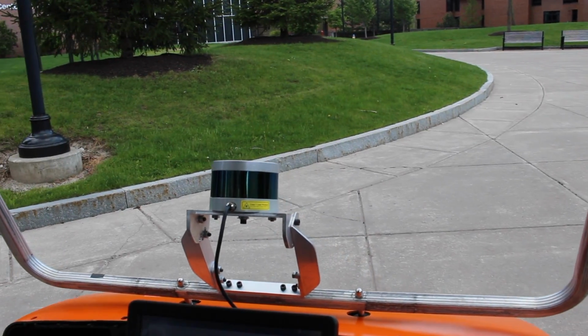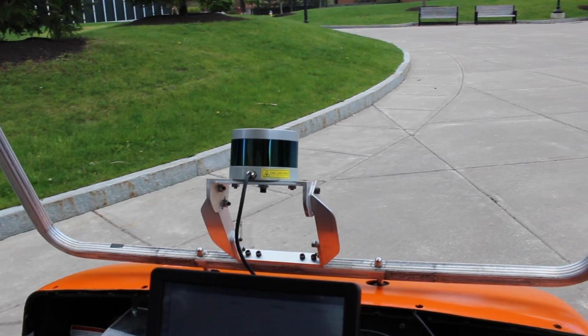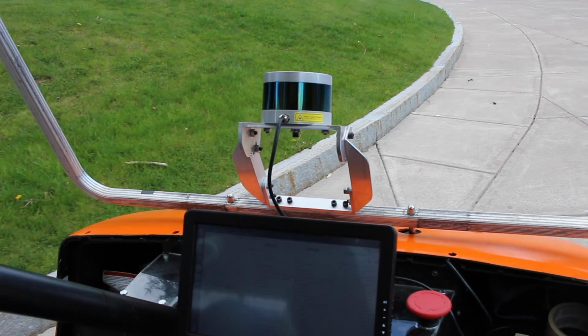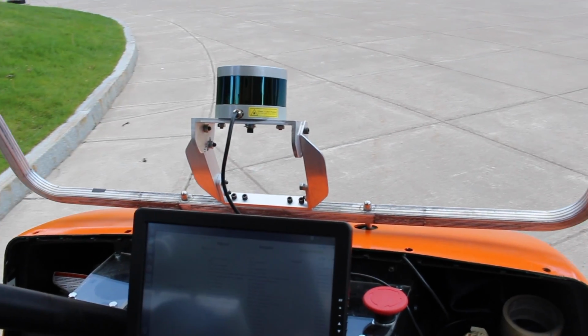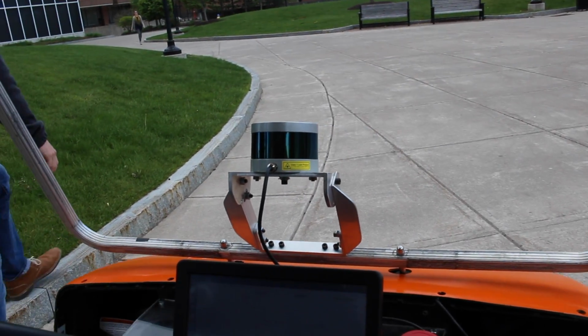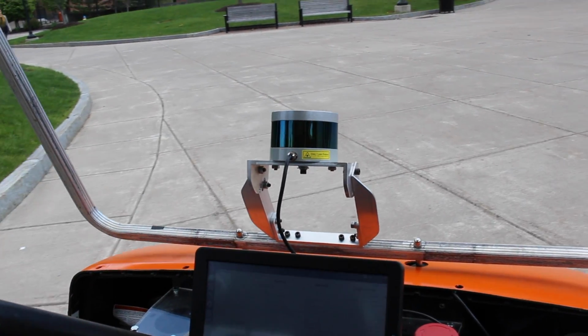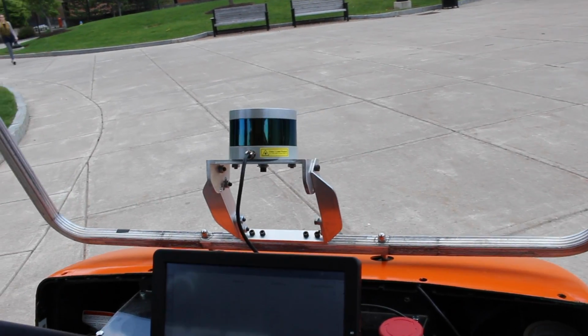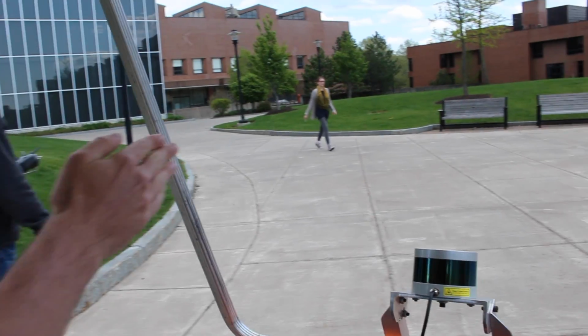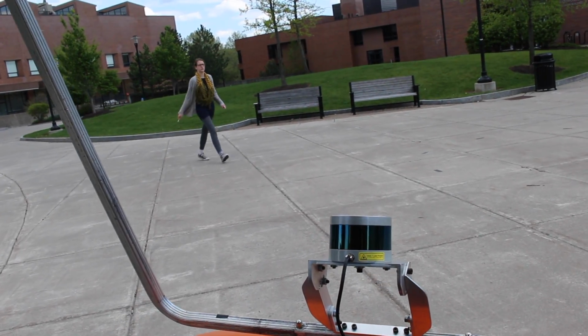You can see what's happening here is as we're driving, our odometry information is degrading, and it's starting to lose the path. Because of that, we're relying on the object avoidance artificial potential field to steer us away from danger. At this point, it most likely believes that the path we're trying to head is in this direction, but it's avoiding the curb because it's in the way.